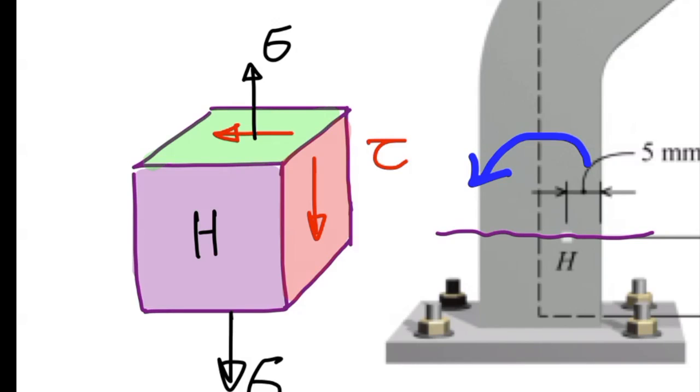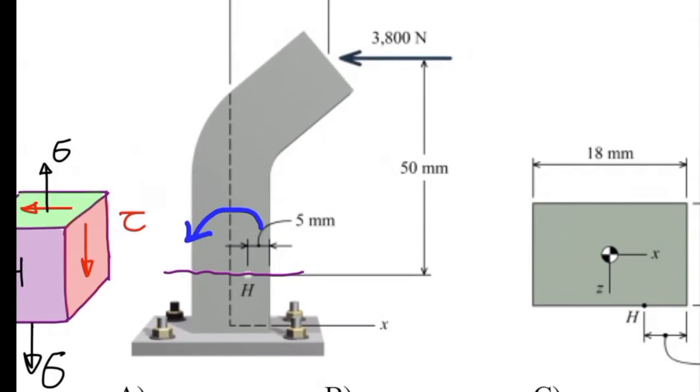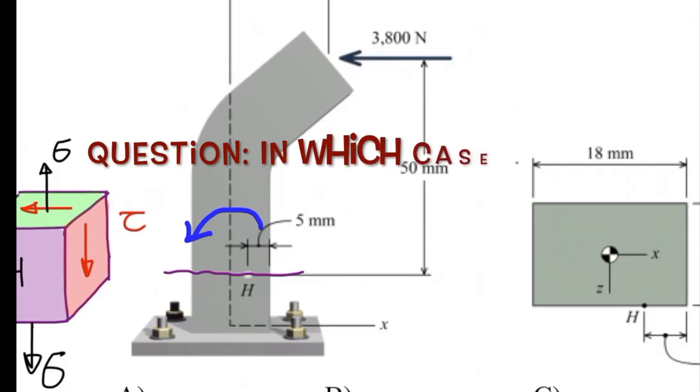I understand that when we look at this problem and see a shear force going in the horizontal direction, we may guess that there should be a stress developed on this side. But in mechanics of materials, when we go over all these steps, there is nothing to produce stress in that red surface with the cut section that we are studying here. So nothing. That would be zero. Does that make sense? Yes, ma'am.